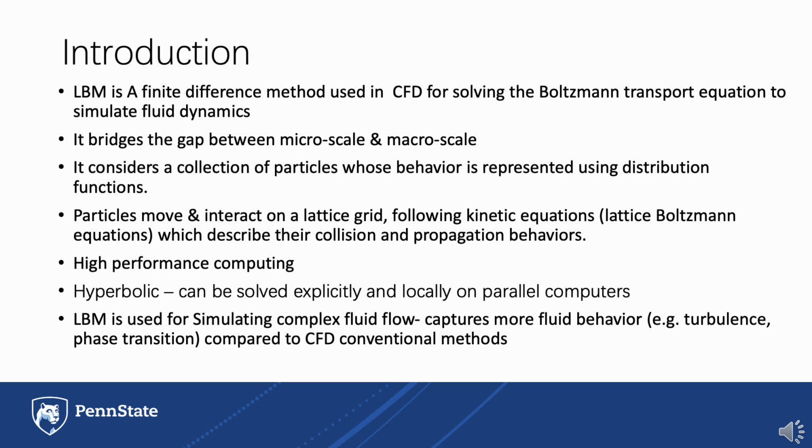So to start off with, here is an overview of what LBM is. The Lattice-Boltzmann method is used in the field of computational fluid dynamics to simulate fluid flow. It is a finite difference method used for solving the Boltzmann transport equation, which bridges the gap between the microscale and macroscale. And we'll elaborate more on the difference between these different scales on the next slide, so hold on to that thought.